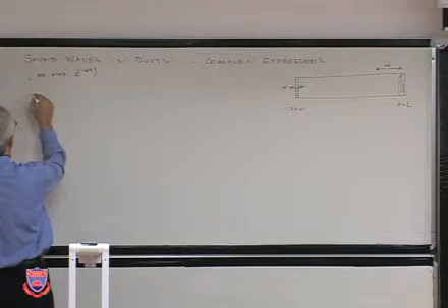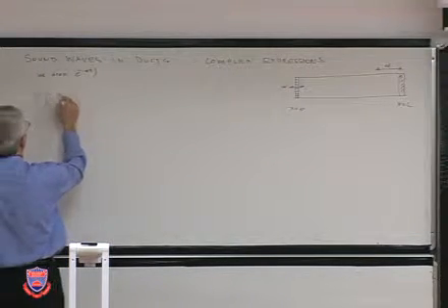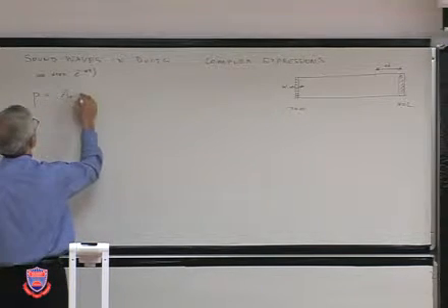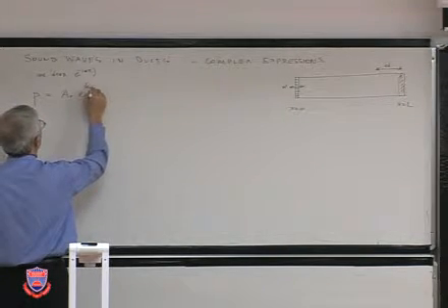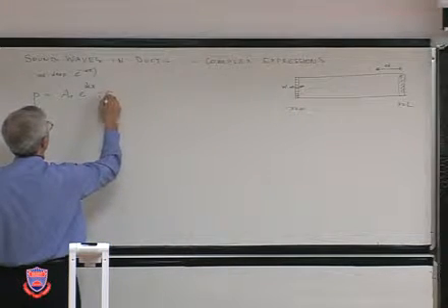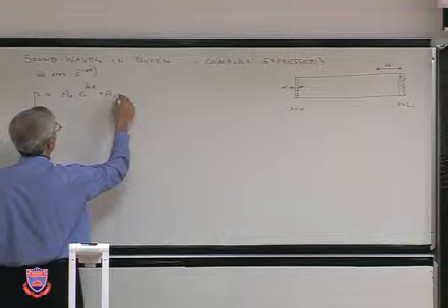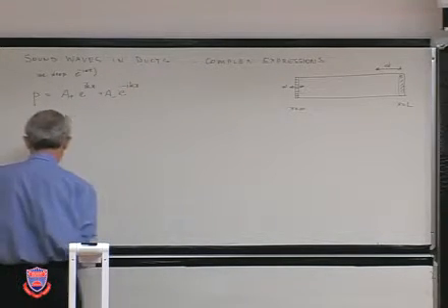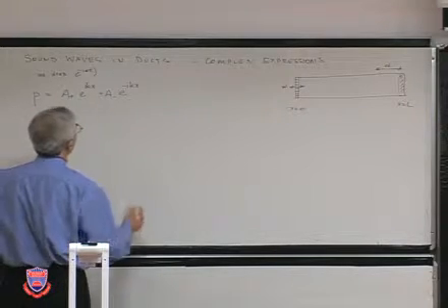So the pressure field in the pipe is an amplitude A plus with a wave that progresses in the positive direction and another amplitude A minus for the pressure that's progressing in the other direction.